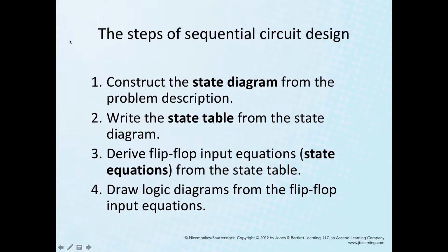So this is the outline of a sequential circuit design. From the given problem description, we construct a state diagram. Out of the diagram, we derive a state table. From the table, we derive state equations. Then that's pretty much it. Out of the equations, you can draw a logic diagram, which is a hardware implementation.